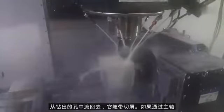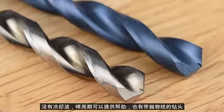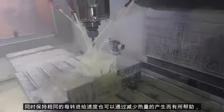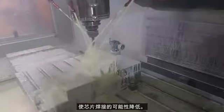If through spindle coolant isn't available, pecking cycles can help. There are also drills with parabolic flute geometry that are designed to more effectively lift chips from the hole. Lowering the spindle speed while maintaining the same feed per rev can also help by reducing the heat generation, making the chips less likely to weld up.